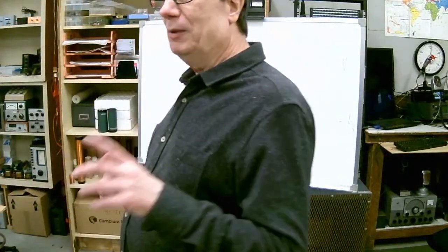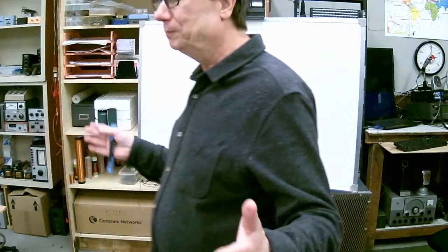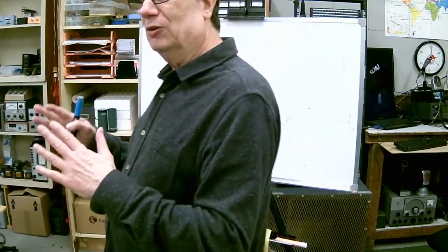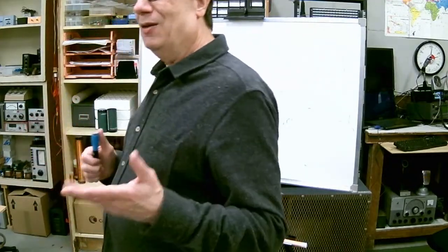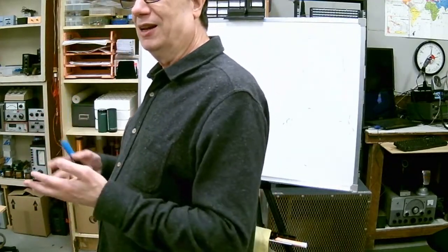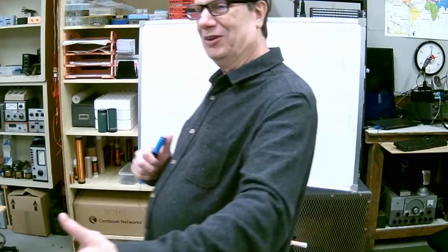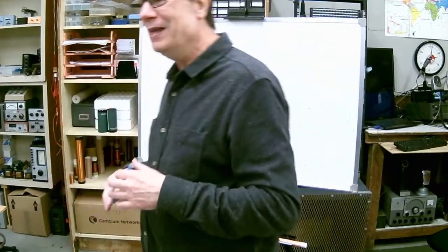But there's still the big problem: the AM broadcast band is a huge range of frequencies. It's a 3 to 1 frequency range at the bare minimum. So as you tune to the top, the bandwidth of the signal got wider and wider. So the Q decreased as you went to the top of the band. Well, what does Q have to do with it? It has to do with the fidelity. The higher the Q, the narrower the audio frequency response is. So the stations down at the bottom will sound very restricted and narrow, and at the top end you get the high fidelity stuff happening at the high end.